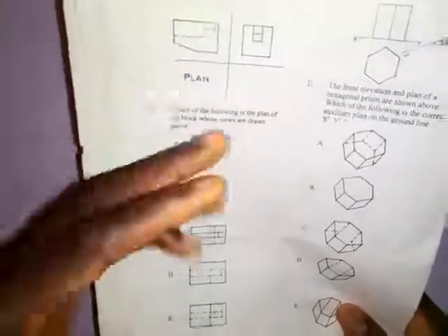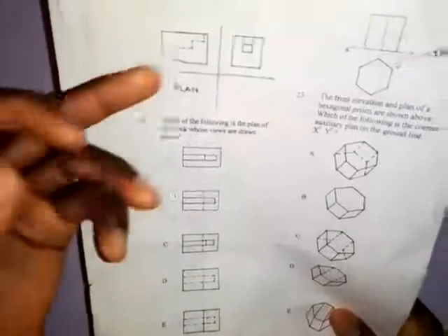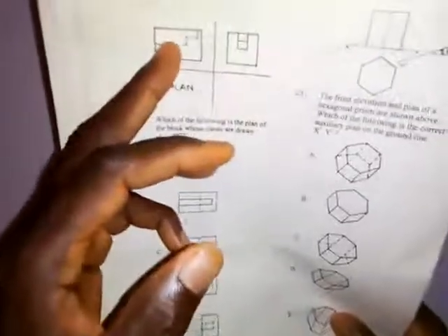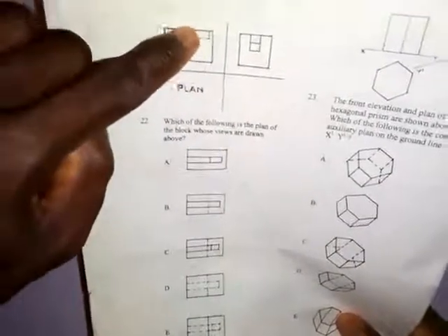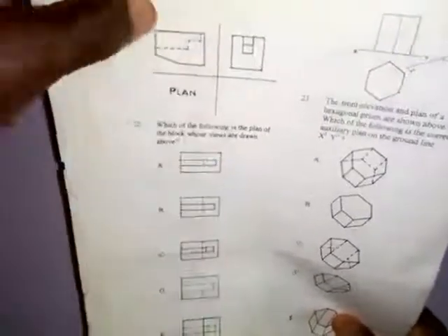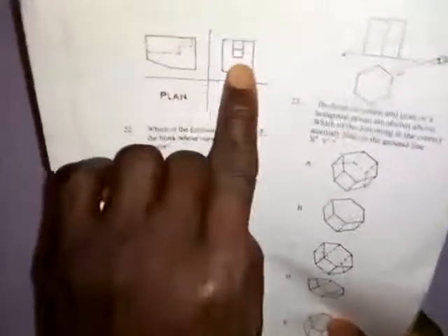So at this point, the object is being viewed. I didn't sketch the isometric view of the object, but the object is viewed in the direction in which this thing that we see here is hidden in the front elevation. So if it is hidden in the front elevation, by the time you look at it from the top, you will see a line at this point, a line at this point, a line at this point, and then this line will go straight. That's what we have here. The line that we have here is what is shown here, and we have two straight lines as we have here. So the correct answer is option A.